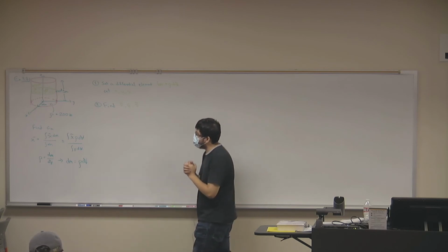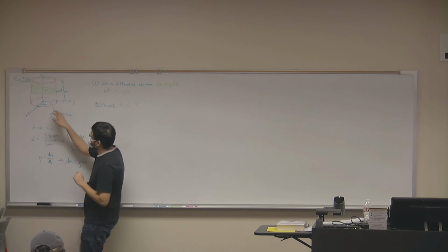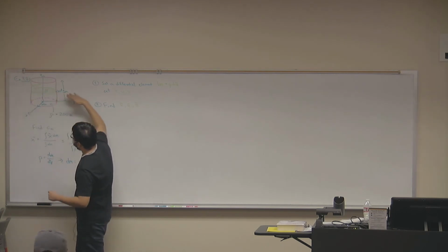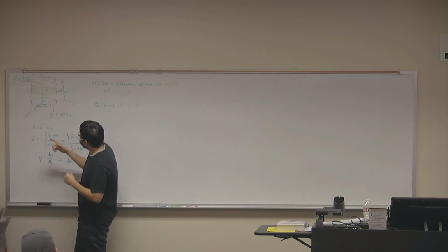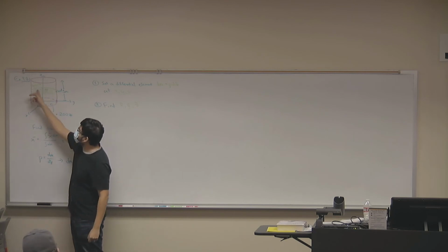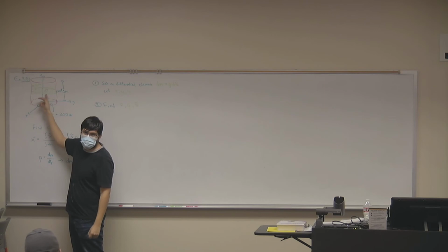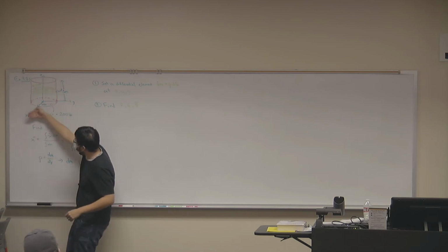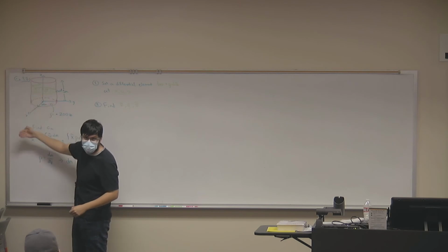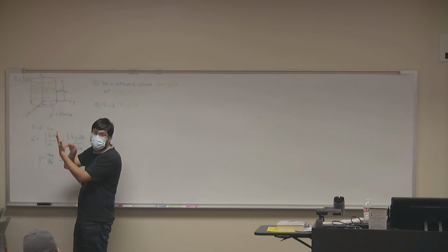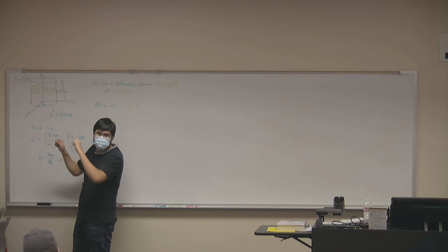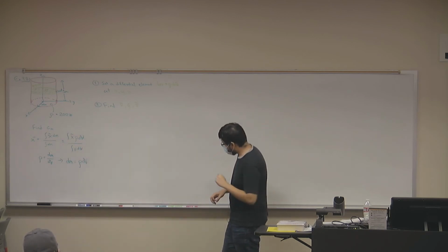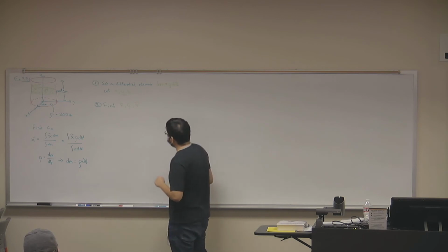Now, if you look at this element, here's why it's important to have set it up this way. Because my element is a horizontal circular plate, does the center of mass vary in the x and y directions for this element? It doesn't, right? And that's good, because if we would have actually set our element to be a vertical rectangle, my center of mass would actually not be in the middle of that element. I would have to still try to find out some way of solving it, okay? So I want to find x squiggly, y squiggly, z squiggly.